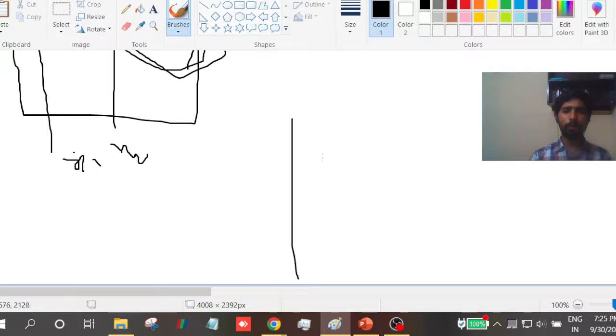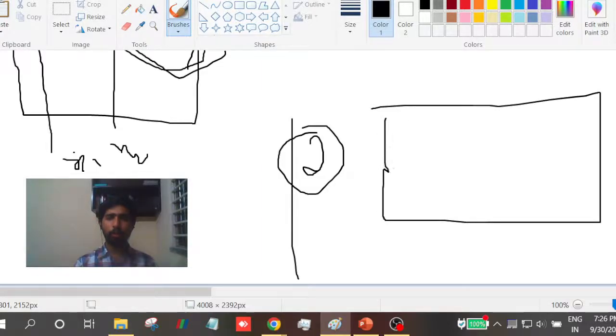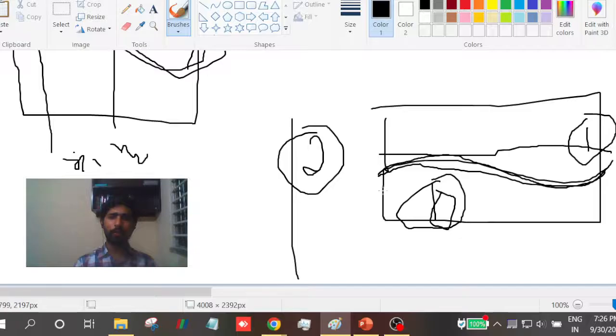Okay, then you have approach number two, which I would say is using the heaviside functions. Where what you will mainly do is that, if I have, say for example, two different phases, I will identify them as 1 and 2, or for example 0 and 1, and then at this interface, so mainly we are getting grids, there is a combination of 0 and 1, so then I'll do some interpolation and then try to solve that, okay. But these are usually subject to some instabilities, because you can see that there is a direct jump which is happening from 0 to 1.